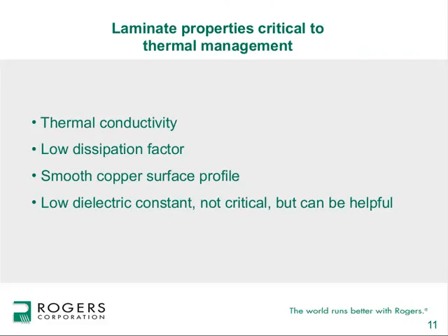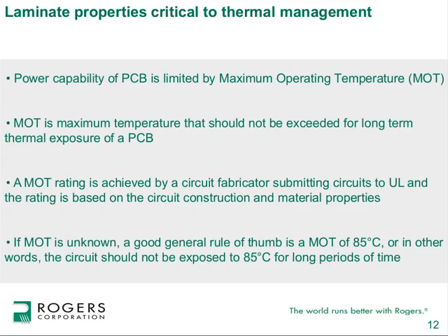So for laminate properties that are critical for thermal management, obviously thermal conductivity is a big deal. I'll talk some about dissipation factor. A smooth copper surface can be very advantageous. And then dielectric constant, which is usually not thought of in the case of thermal management, but it can be beneficial in a couple of regards.